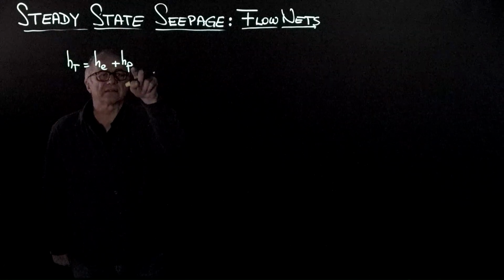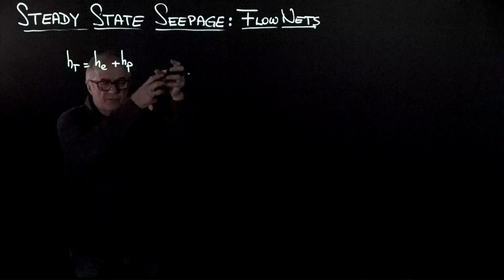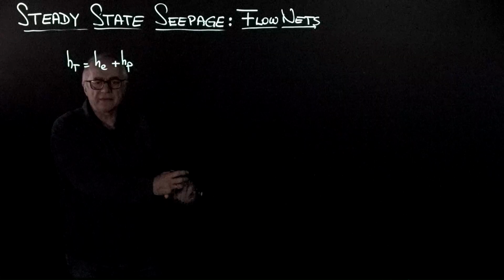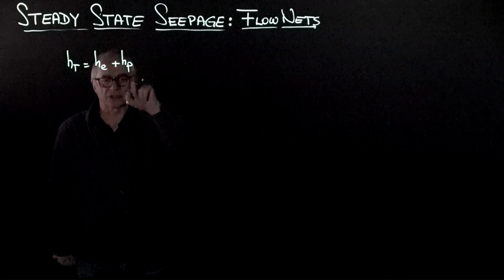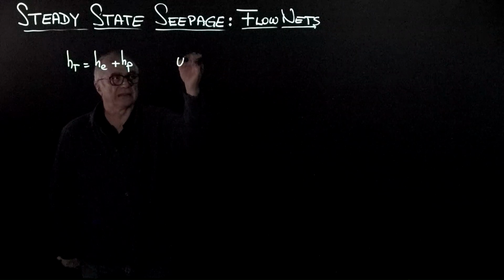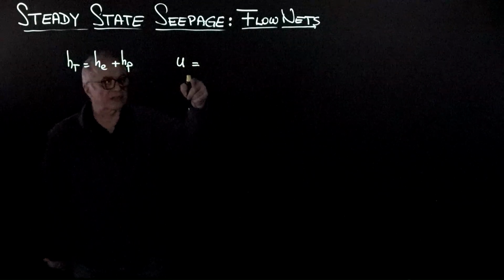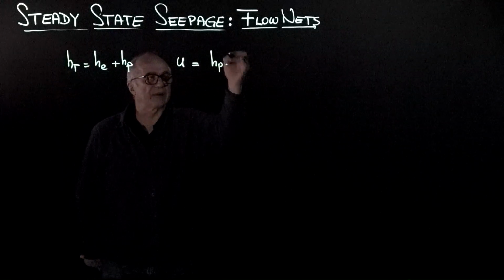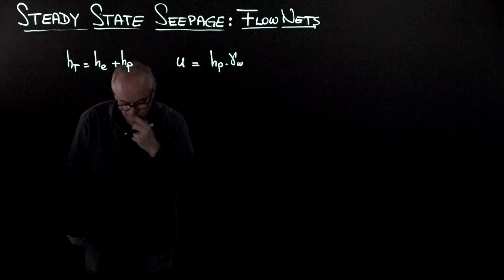So this is a good mental model to have. Whenever you are confused, just put in your mind a pipe at the location and estimate how high the water rises. That's the pressure, and indeed the fluid pressure that controls effective stress and the shear strength is going to be equal to H pressure times the unit weight of the fluid, in this case water.